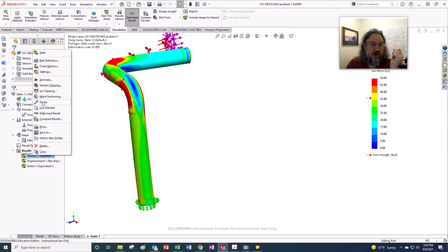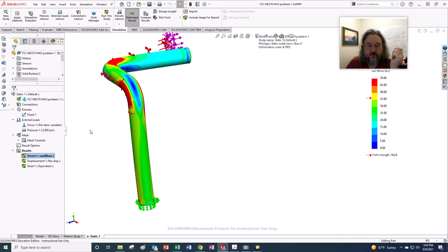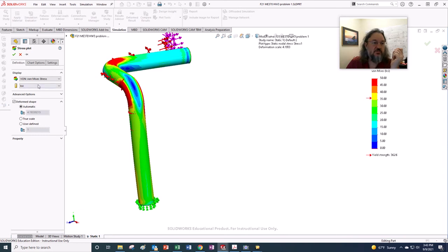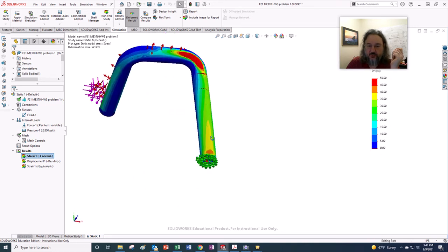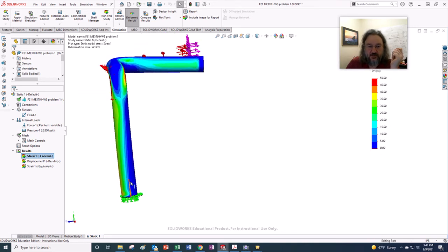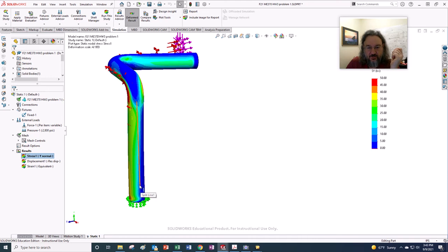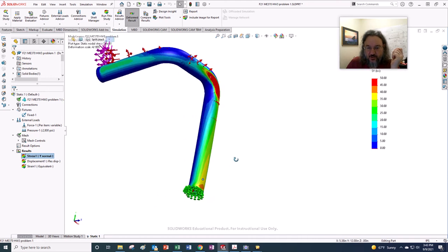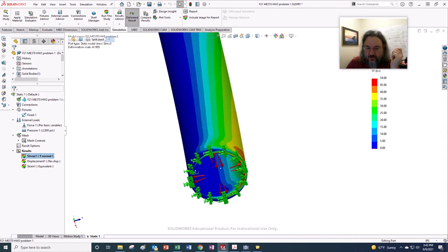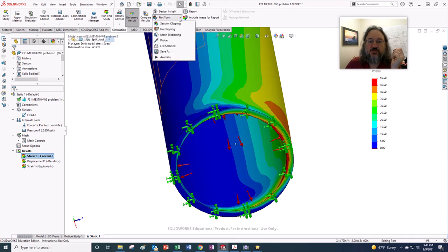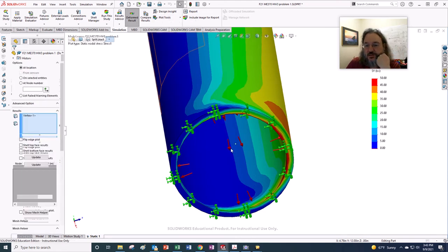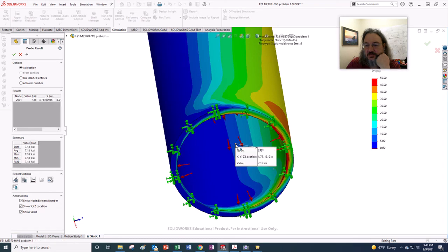Okay, so I want to actually look at some values here. In the y direction, let's take a look at the normal stresses in the y direction. I'm just going to leave the scale I have here. You'll notice I have a nice scale from 0 to 50 counting by 5s. Isn't that pretty? I want to double check that I'm getting the right point, because the orientation can get a little lost as we try to balance it. I'm going to pick that point, zoom in down here, and hovering, I'm picking that point. I'm going to use the probe tool here, and I see it disappears, but we got that right there.